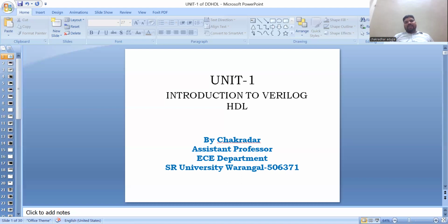Next are underscore characters and question marks. Underscore characters are always allowed anywhere in a number except the first character. You cannot use it as the very first character. Underscore characters are allowed only to improve the readability of numbers and are ignored by Verilog. A question mark is an alternative for Z in the context of numbers. It can also be used as a ternary operator, and it is used to enhance readability in casex and casez statements also.